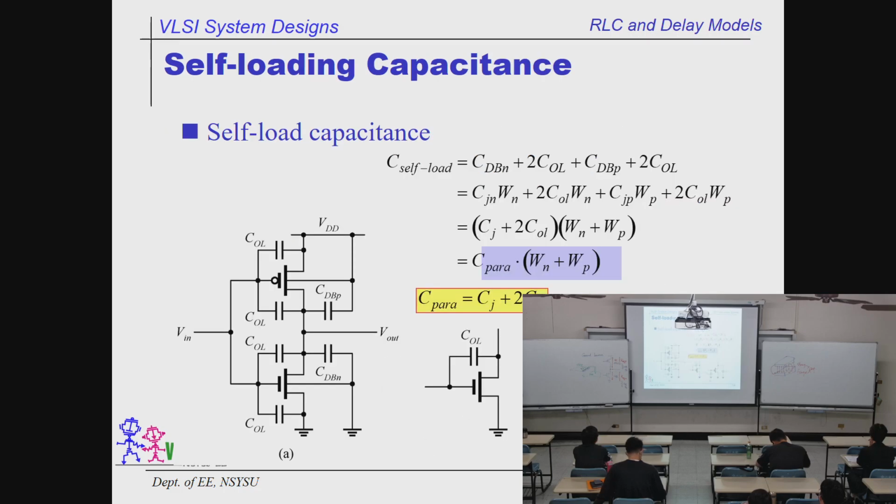So how do we do that? Okay, we look into all of them one by one. So the first one we run into is the load created by myself, by the driver. So how many capacitors here? See, you'll feel dizzy. It's like a maze. Don't panic. Don't worry. Okay, this is overlap created by this PMOS. These are 2 overlaps created by this MOS. And the overlaps over here can be decomposed into 2 parts.